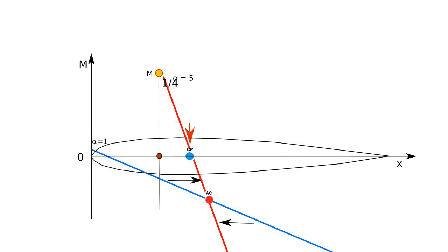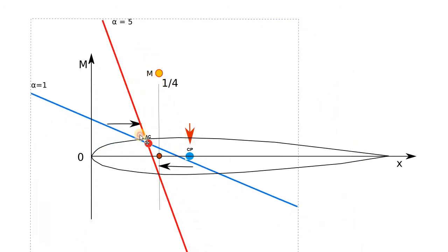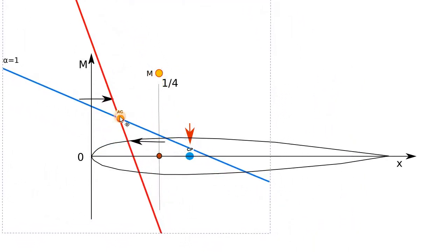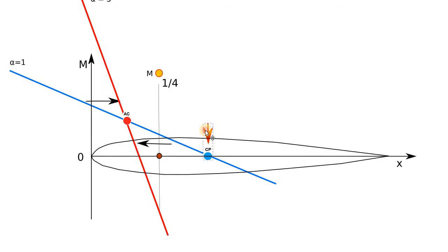And as we have seen previously, you can put the center of gravity somewhere here in this range, depending on the angle of attack at which you operate. Okay, so now what happens if, for instance, we have the opposite situation, when the aerodynamical center is located in front of the center of pressure. So in that case, the center of pressure moves close to the nose. And this is not good, as we have seen previously, because the airfoil becomes unstable.